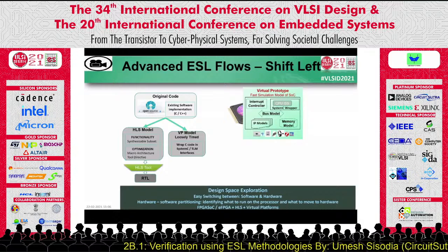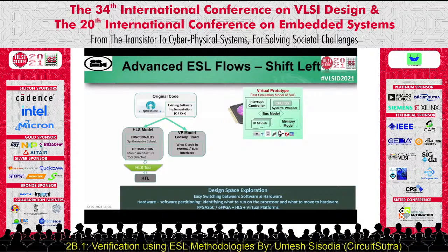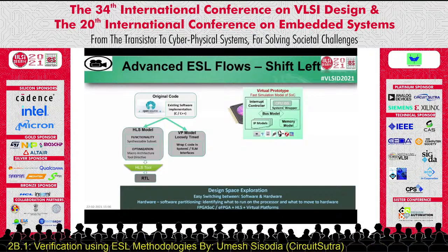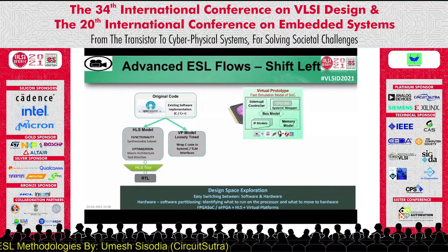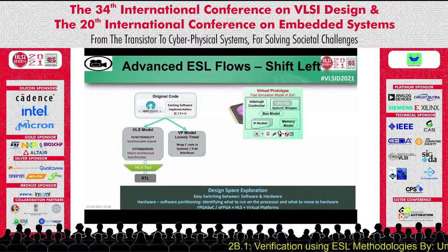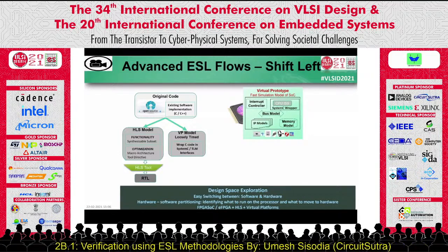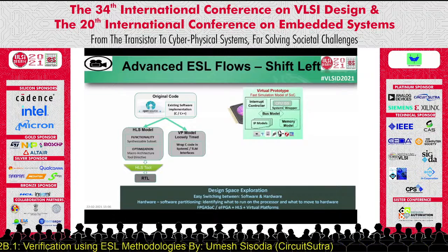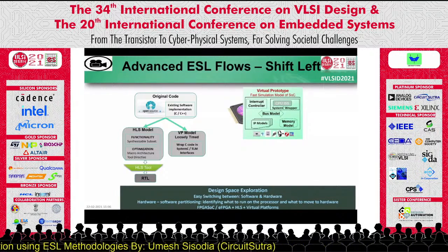But if we are starting from an existing software implementation, then at least we can have a common starting point. The same software implementation can be refined to make it synthesizable for HLS, or can be wrapped in SystemC or TLM for the virtual prototyping case, further using techniques like loosely timed temporal decoupling, etc. We implement a common set of regression suites which can be used to verify both these kinds of models.